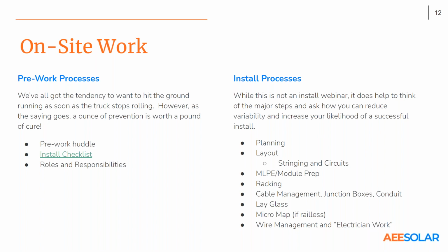MLPE and module prep. One of you guys had this adage as we were putting these slides together, that the least efficient time is time up on the roof. So everything you can do on the ground to prep modules, MLPE, racking even, and we'll talk through some of that, the more of that you can do on the ground, the quicker you're going to be up on the roof. What we like to say, Josh, is time on the ground is cheaper than time on the roof, and time in the warehouse is cheaper than time on the ground.